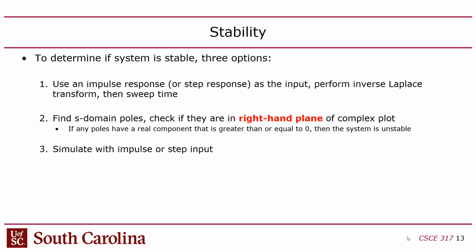Now, what's Simulink doing? Simulink is simulating the differential equations. And to do that, you have to use a numerical integrator, a solver. So there's a solver as part of Simulink that is numerically going from the S domain to the time domain, right?